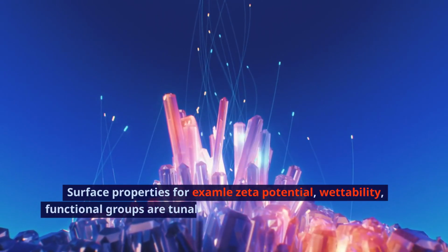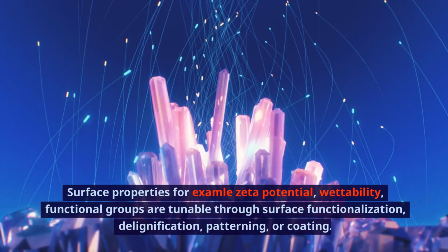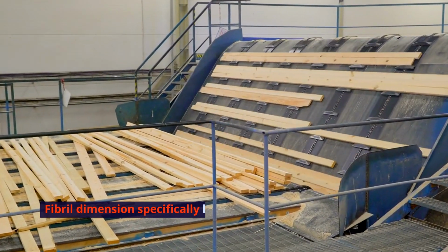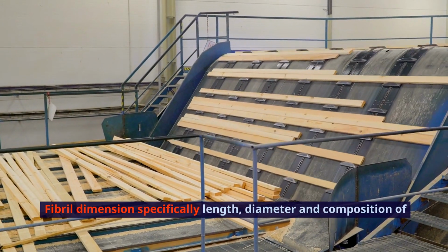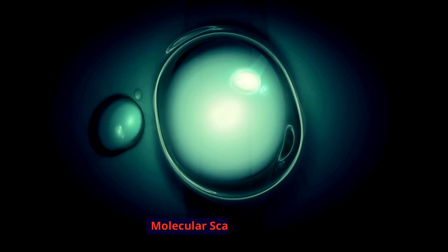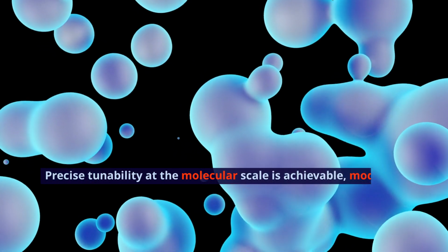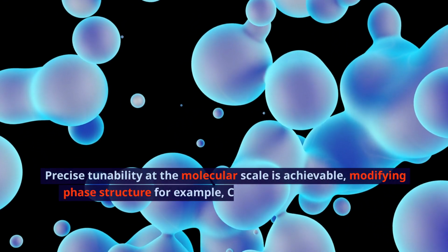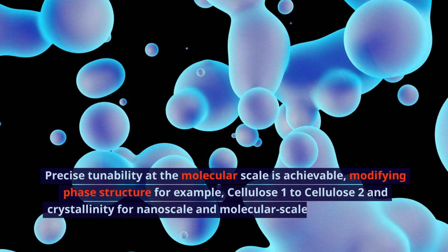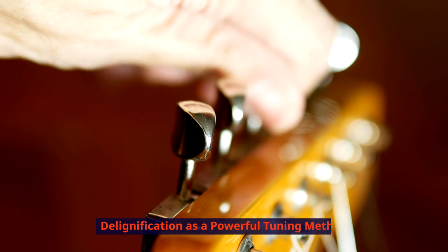Functional groups are tunable through surface functionalization, delignification, patterning, or coating. Fibril dimension and composition tuning. Fibril dimension, specifically length, diameter, and composition of wood-based structures, can be tuned for diverse properties. Molecular scale tunability. Precise tunability at the molecular scale is achievable. Modifying phase structure, for example, cellulose 1 to cellulose 2, and crystallinity for nanoscale and molecular scale regulation of ion transport.